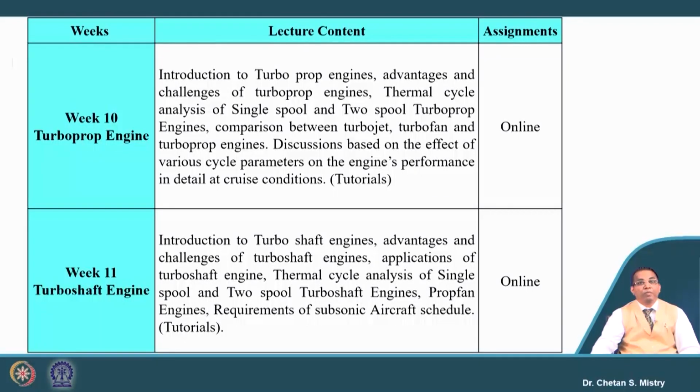Then we discussed the turboprop engine, where the whole thrust we are focusing on is based on the propeller. So basically the propeller was generating the thrust, and we have seen the research and ongoing applications that show thrust generated by the propeller as well as by the exhaust of the gas turbine engine. So we had two thrusts coming: one because of the propeller, and the second because of the exhaust from the nozzle.